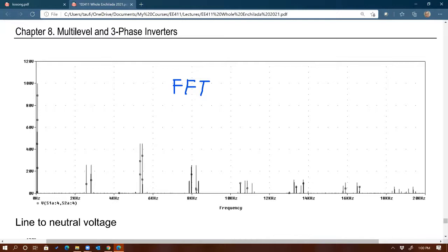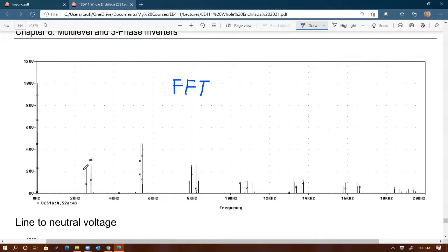Further out, so easier to filter out. Yes, you can see the locations, right? Locations of the harmonics is away from 60 hertz, right? Further away. Instead of, remember before, 5 times, 7 times, 5 times 60 was 300, right? So 300 hertz for square wave.